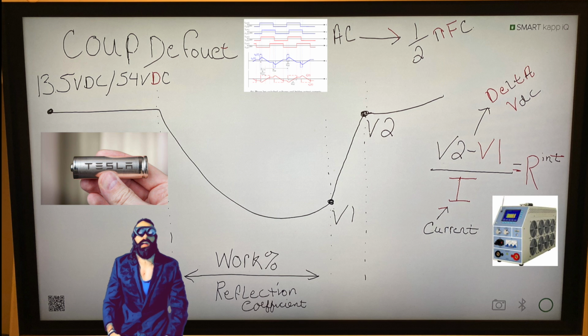I often use an analogy when I'm looking at batteries and testing and commissioning them around the world: I have no idea how fast you can run a mile. So what I need to do is make you work. And how we do that with battery systems is by putting them under a DC load bank, a DC resistance for DC current. But if I wanted to average you out, if you're running different 1,600 meters, what I need to do is have you run 1 mile at 6 minutes, and then have you run 2 other miles after that at, as close as you can, 6 minutes. Now I can implement an averaging algorithm.